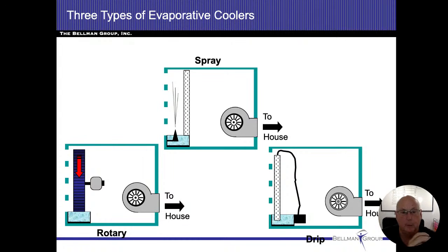One of the items people use for air conditioning is something called an evaporative cooler. Now it has a nickname of a swamp cooler as well, and it works on the principle of, again, changing state. So instead of using refrigerant going from a liquid to a gas to absorb heat, it actually uses water, and it uses it on the principle of if I add humidity to a building, and that moisture lands on people, it lands on objects.